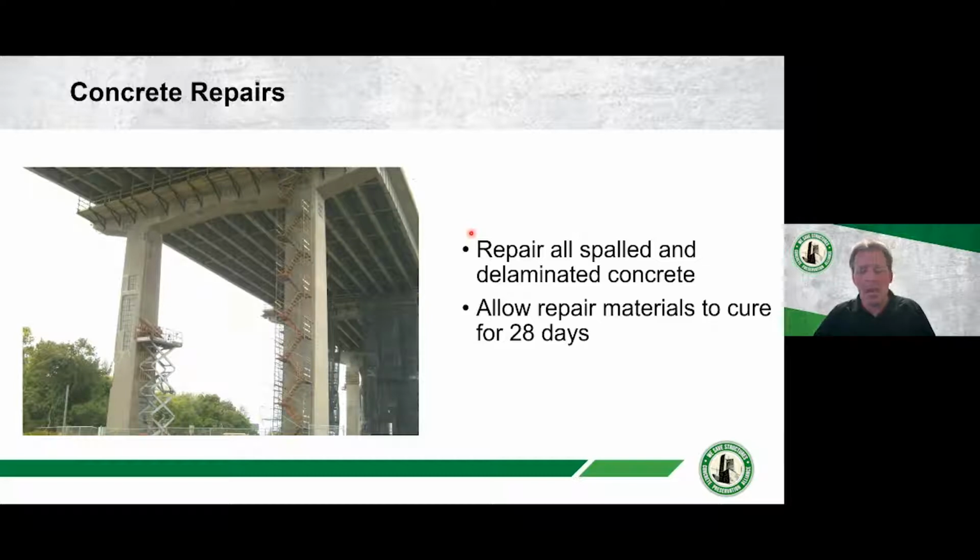It's not uncommon nowadays to see that time frame reduced to around 14 days. It's just found that you can spray it after 14 days if you're using a high performance repair mortar and you don't jeopardize any bond strength.